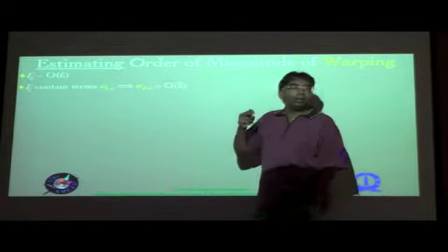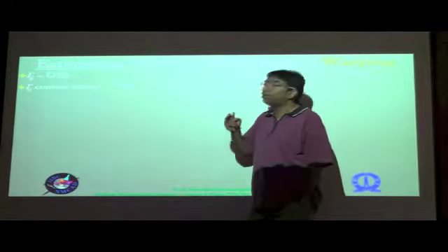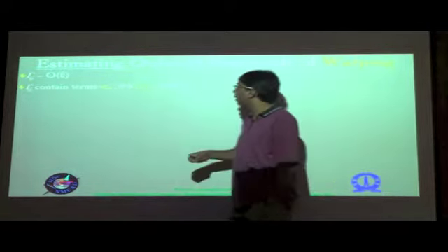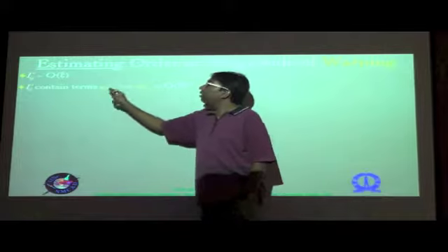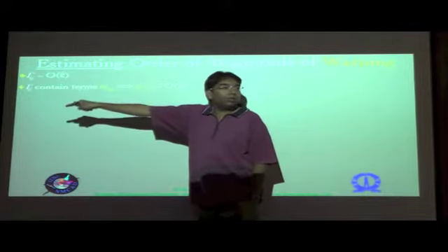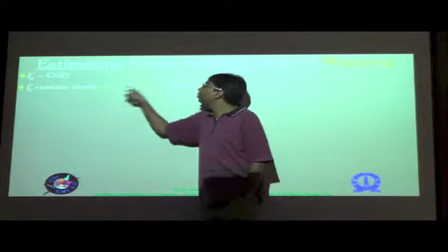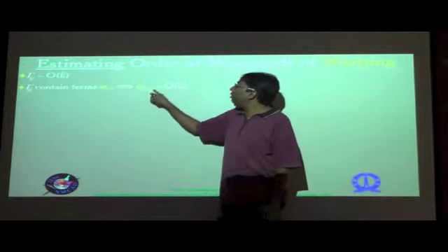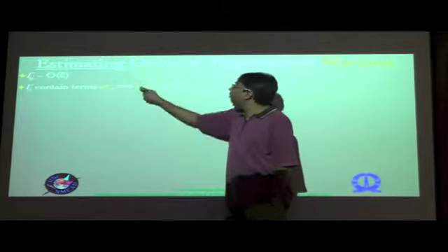In particular, the gammas would be gamma 2, 2, gamma 3, 3, gamma 2, 3. Those are the places where you would find the things that we typically need. And of course, gamma 1, 3, 2 in order to determine the W1 as well. So what that means is that because that is one of the terms there, that term cannot become bigger than the strain, otherwise its contribution to the strain will be very large, and therefore the strain itself will become large, and therefore those kinds of terms should also be of the order of the strain itself, which is order of epsilon hat. Now we know the order of x alpha, which is basically the cross-sectional dimension, and therefore from that you can determine the orders of each of the W's.